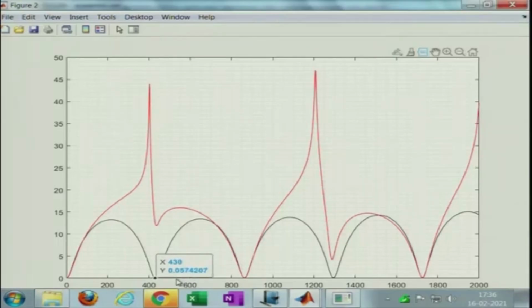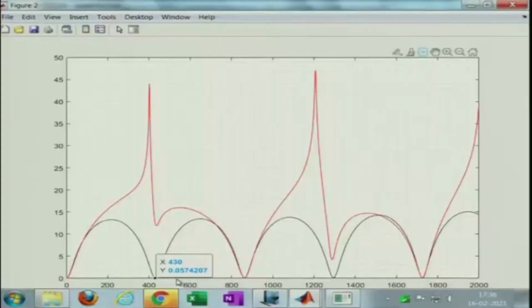Now, we remember for an extended concentric chamber with extensions at the inlet and outlet, if we just had a tube with L by 2 length, theoretically it would have exactly tuned the performance. We saw that. Okay. But that does not really happen because of end correction effects. There were some end corrections. You would also have done some assignments related to that in the last couple of weeks or so. But here we are deliberately choosing L by 2 and assuming only plane waves, and still theoretically able to tune the performance. Okay. And that is really because of the perforated impedance.